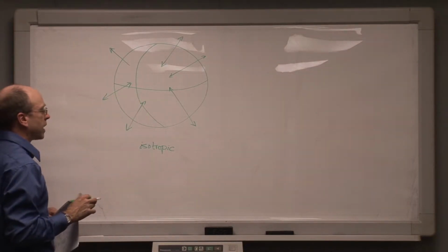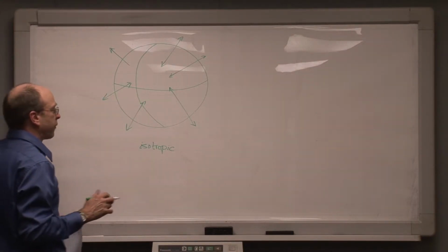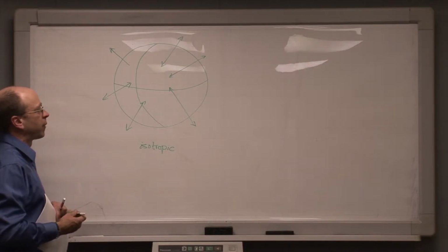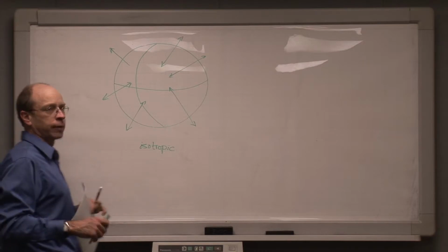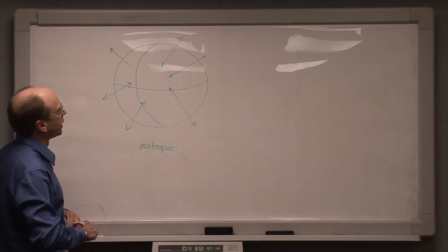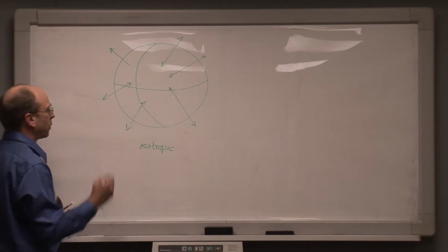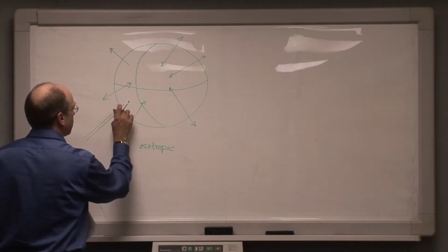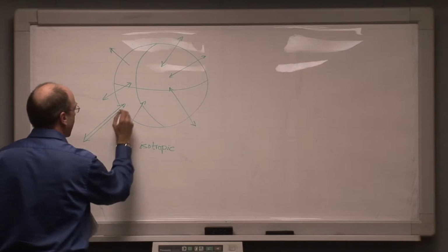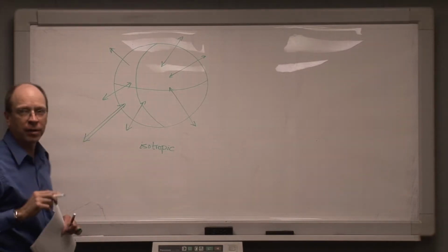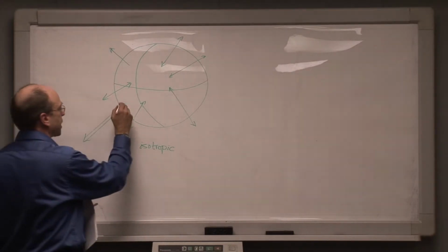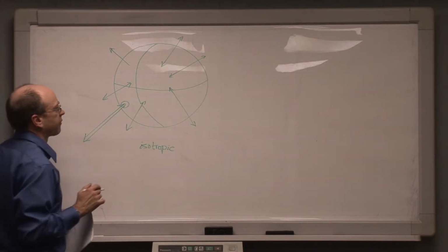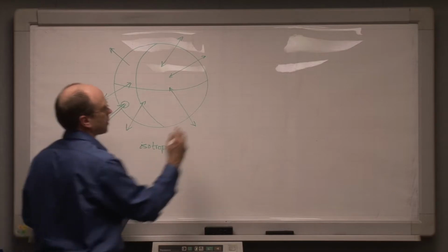I do not believe that any isotropic antenna has ever been physically realized as such. It has occurred to me that if we heat a piece of metal to a high temperature and let it radiate, it will radiate isotropically. But in terms of building a practical antenna, the problem with building something that would be truly isotropic is that somewhere, somehow, you would have to get energy in and out of the antenna through a circuit connection, and it would probably be hard to do that in a pure sense without somehow disturbing the overall isotropic characteristic of the antenna. But it is possible to come close.